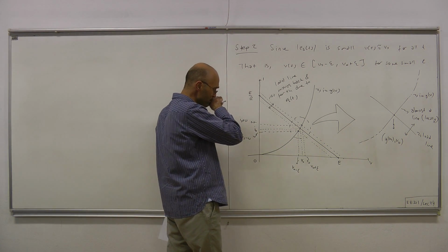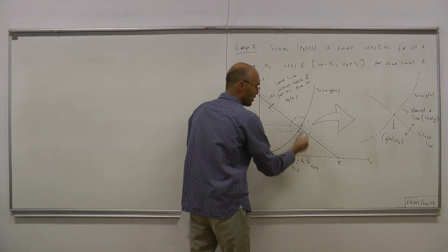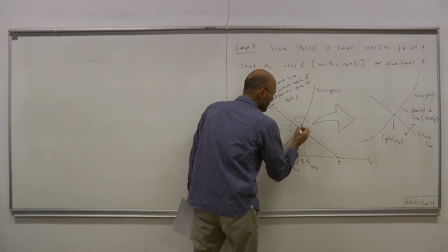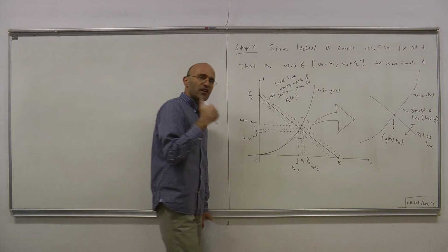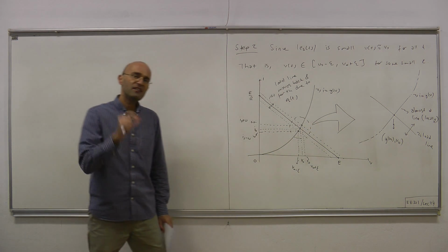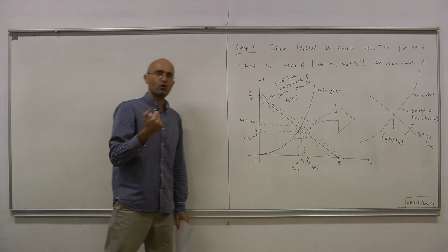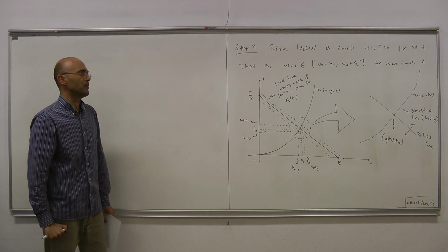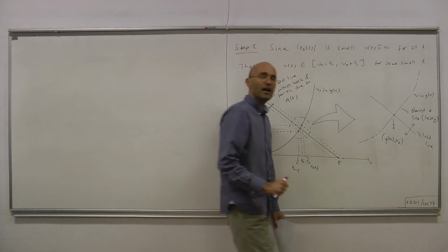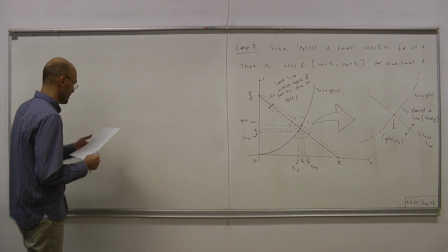Then in step 2, we made the following observation: because the magnitude of S of t is small enough, the solution V of t and I of t will be confined to some neighborhood of V0. And in that small neighborhood, the I equals GV curve, the terminal equation of the nonlinear resistor, can be represented by a line. Let's see what happens if we go with that approximation.